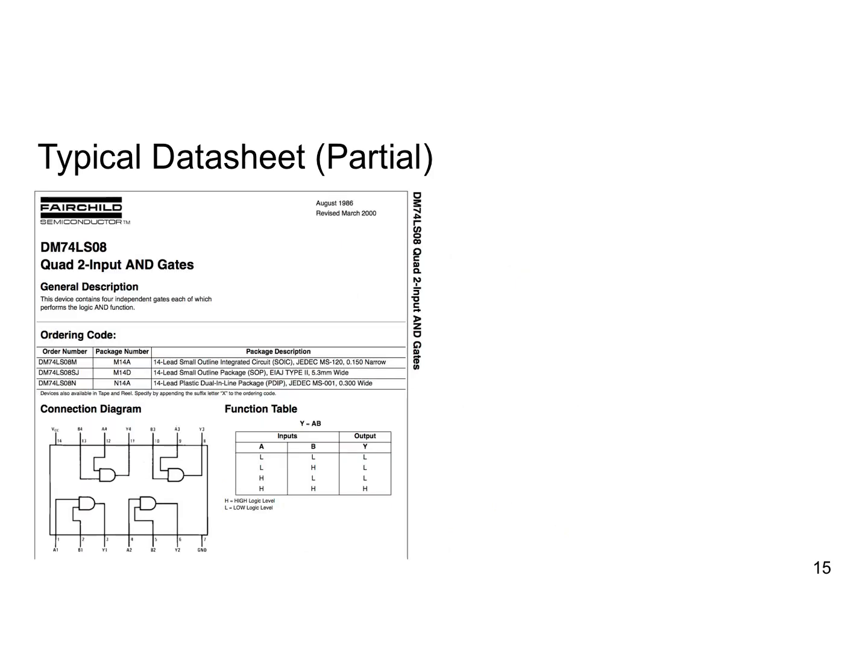Okay, so we're going to have a look at a data sheet. Again, it doesn't matter which one we look at, because they're all going to be the same as far as the voltage and current levels go. Propagation delays will vary depending on the particular device, because an IC with more transistors takes longer for a signal to work its way through. We'll look at propagation delay in a bit, but the voltage and current levels are the same.